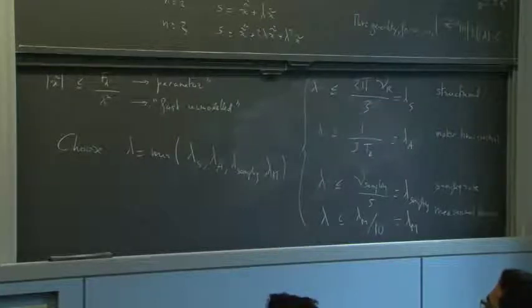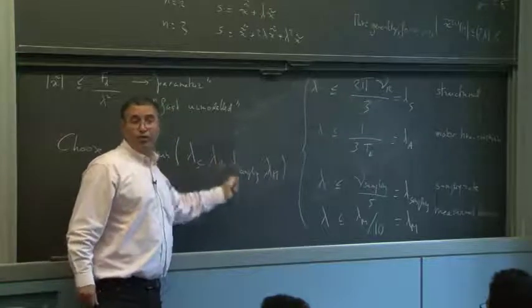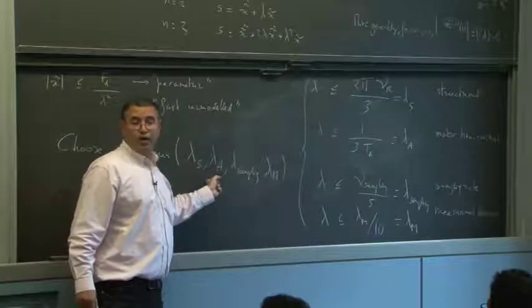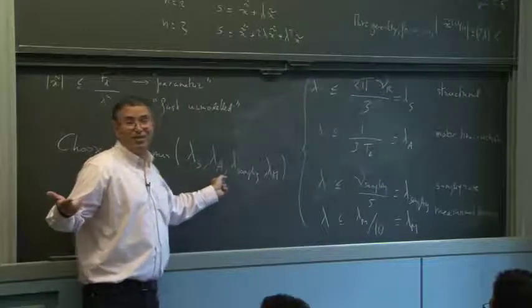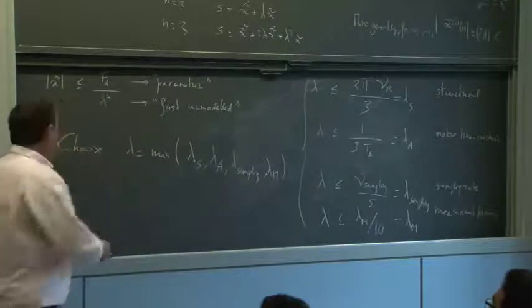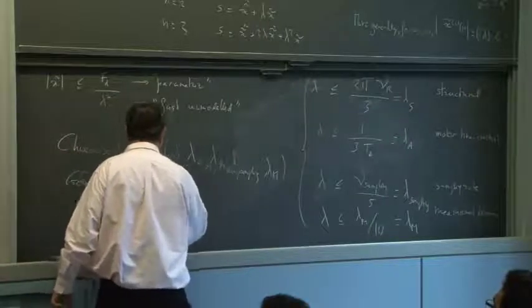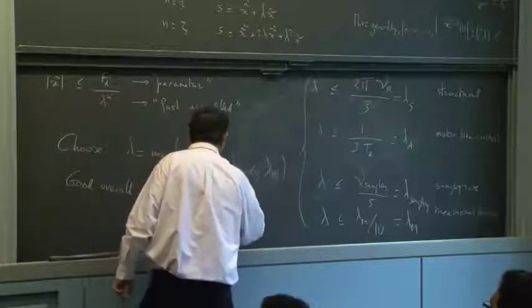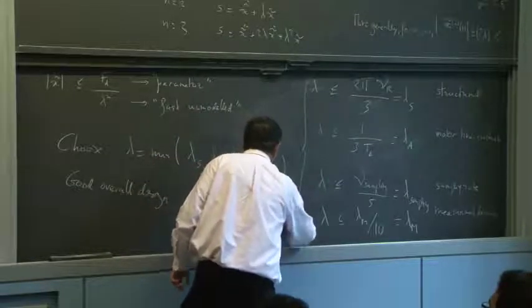It means that for the system to make sense overall as an engineered design, these numbers should be pretty close. If you have 1, 2, 3, and 10, something is really wrong with this 10, not because it's too big, it's unnecessarily big. So for a good overall design, these should be roughly, and here it's really roughly, within a factor of 2, of the same order of magnitude.